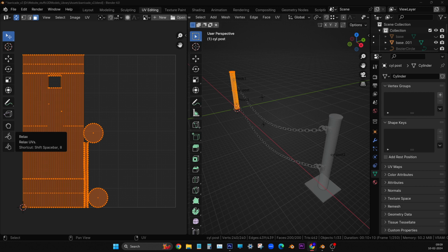This fill opacity 0.25 is the color of the lines it is going to take a snapshot of. If it is too bright, it will be too much. We don't need that, so 0.25 is okay for us. Yeah, this is the default setting. So now you have named it, export UV layout. You can press. Okay, now you can save the file because you didn't save the file.